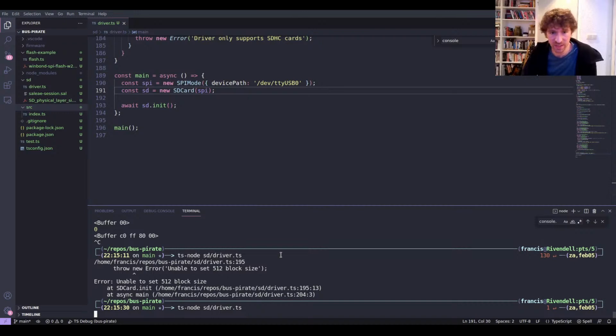And as you can see, the device is now just hanging, and that is because we have an open communication channel with the bus pirate. So at this point, we successfully initialized the SD card. We're ready to start talking to it, extracting data from it, getting bytes and stuff. And that is what we're going to do next week, because this stream has gone on too long already.